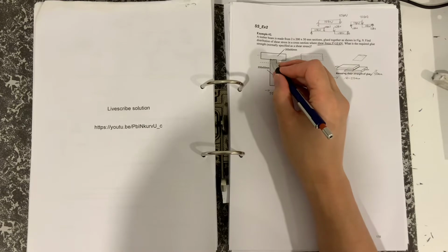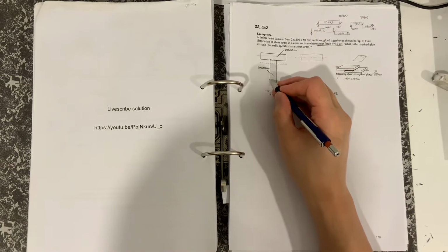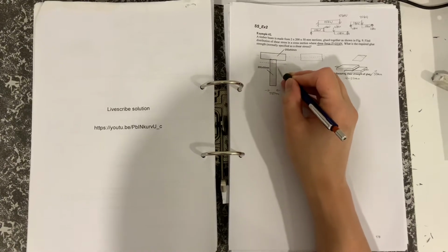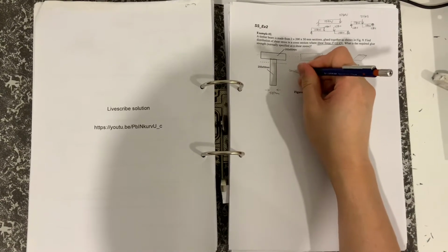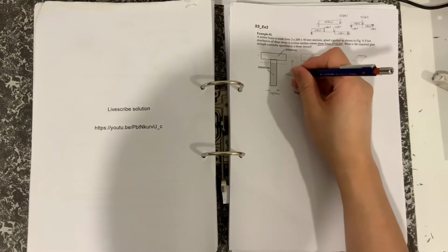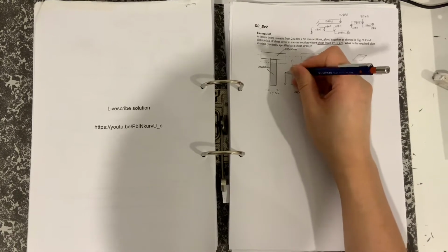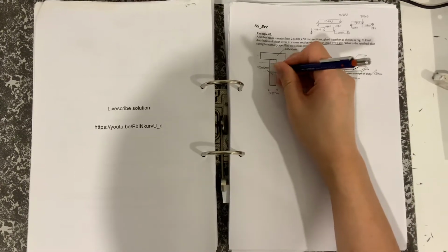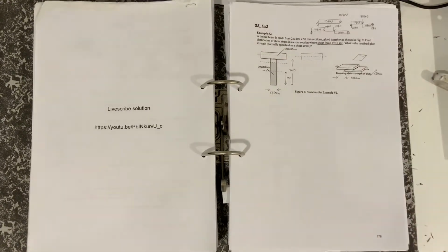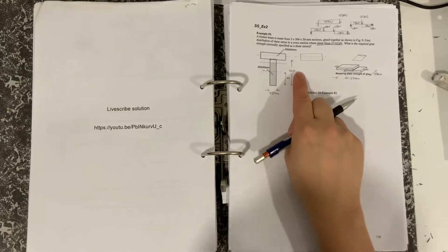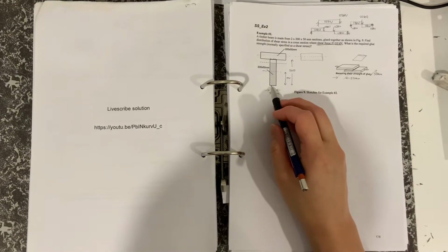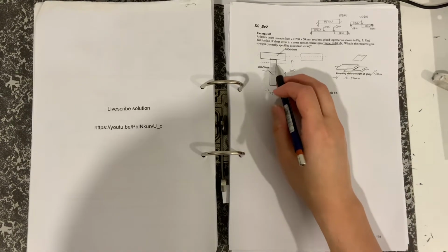And then we've got this second bit here, and the second moment of inertia of this one here about its own neutral axis. So if that was 200 millimeters, then at 100 millimeters, which would be halfway up, that would be its neutral axis. And the second moment of area, or the moment of inertia of this one here, would be 1/12 times the breadth times 200 cubed.